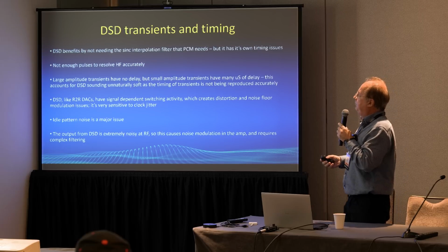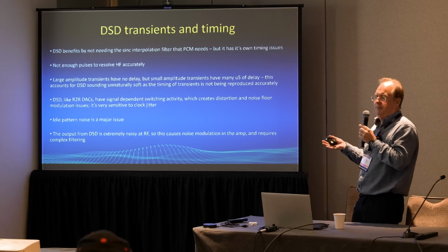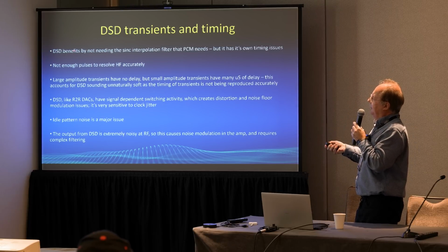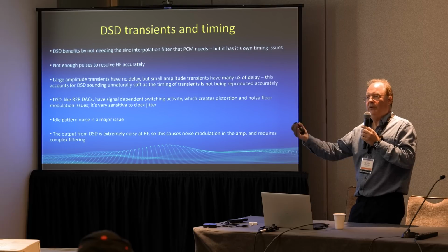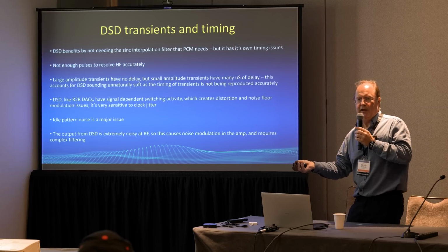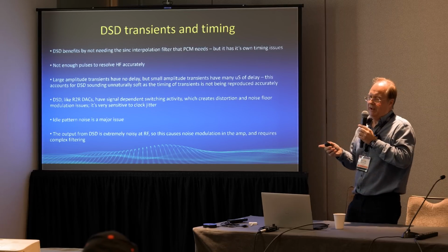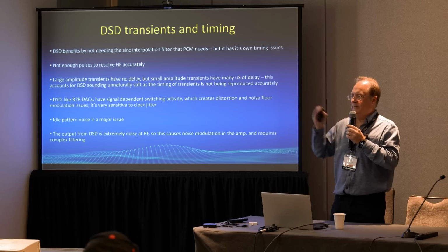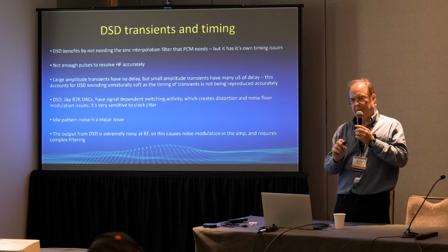The other big issue with DSD is that it's got problems with high-frequency transients. The benefit of DSD is you don't need a sync interpolation filter because it's just the original data. You don't need a complicated interpolation filter, so you don't need an M-scaler. You don't need to worry about those kinds of issues. The downside is that large amplitude signals get through the 1-bit quantizer faster than very small signals.